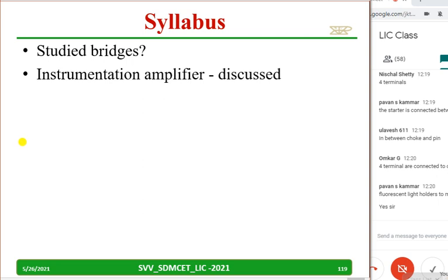Why will the tube glow even once it is on, if you remove the starter? Without the starter it will never glow. Remove the starter and switch on, it will never glow. But once it is glowing, if you remove the starter, then also the tube light will glow.